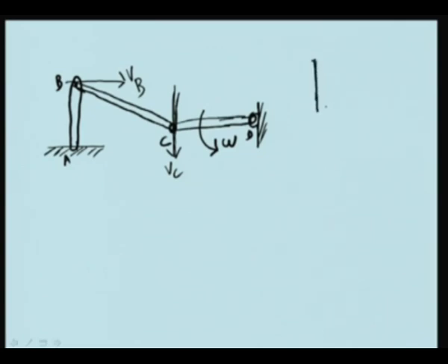This is, you draw a horizontal line passing through this one. So, that means draw a vertical line here, draw a horizontal line here. This is AB. So, these are meeting at this point, therefore, this is called the instantaneous center of rotation of this one.